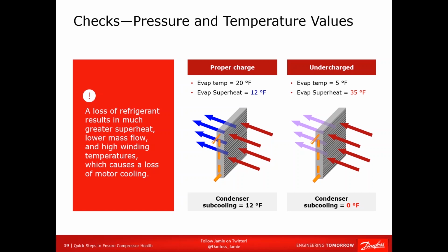That tells me you have a solid column of liquid leaving the condenser, a solid column of liquid going through the metering device and being fed to the evaporator, because all three of these symptoms tell me that you have an appropriate amount of superheat. You got a strong evaporator temperature and good superheat. Now let's jump to the one on the right.